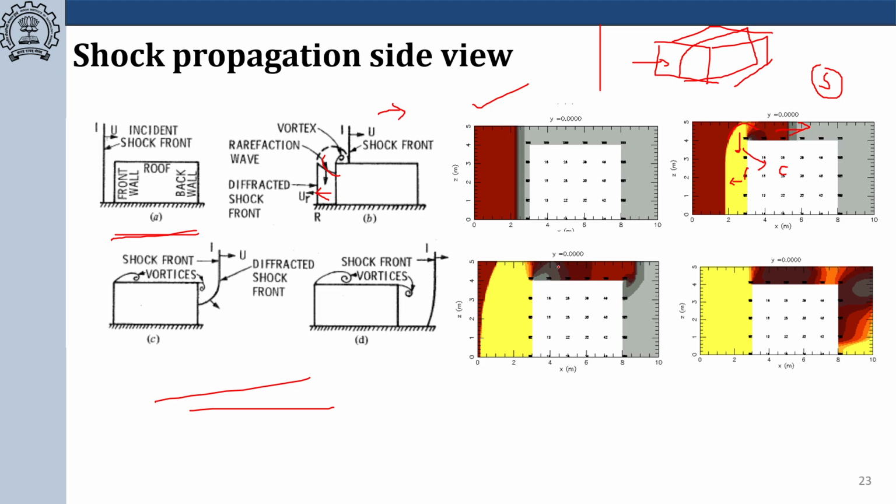As the shock front moves ahead and reaches the other end of the structure, again you have diffraction. Whenever the wave front hits an edge, you will have a diffracted wave, the energy decreases, and a vortex region is formed. The pressures always tend to decrease faster in these regions, so you should be careful while measuring the pressure histories here.